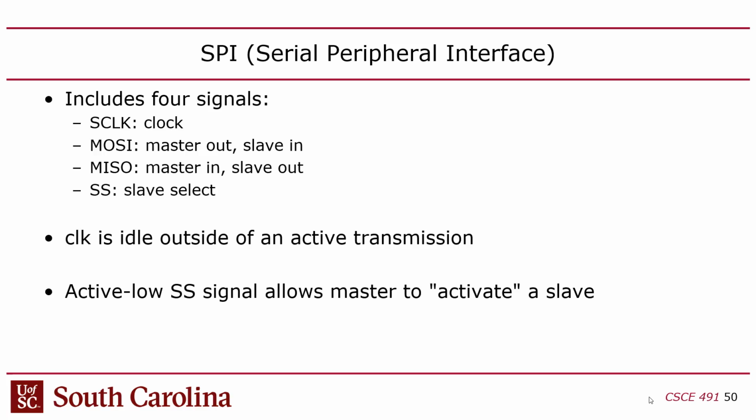So there's S-clock, MOSI, and slave select, which are all outputs from the master, and then the slave kicks back one signal to the master called MISO. MOSI is master out, slave in, MISO is master in, slave out, and this creates a true full duplex bidirectional connection. So I can send and receive bits at the same time, even though that's almost never needed.